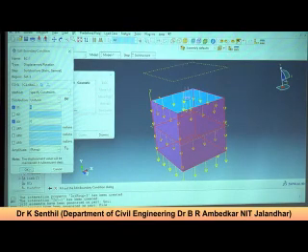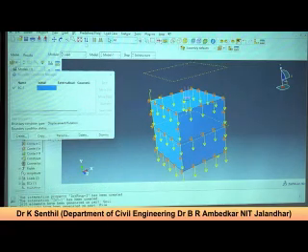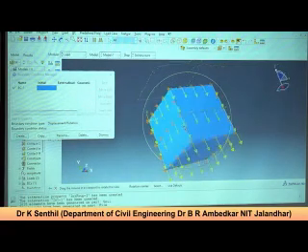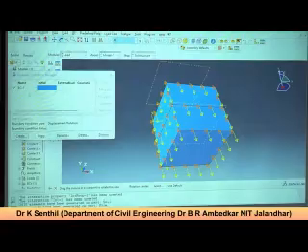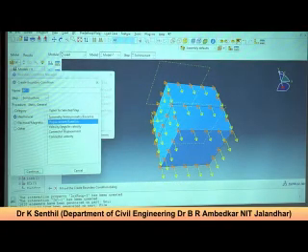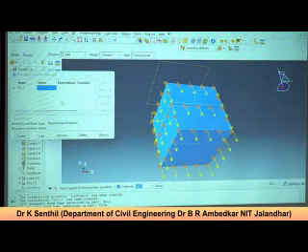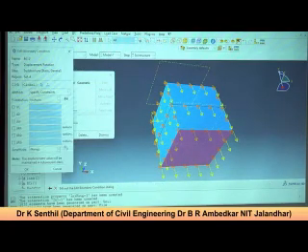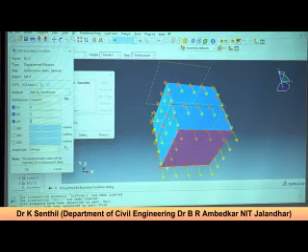Done. Now it's okay. Now at the bottom, I'll keep it fixed. Create displacement. You can select the surface and then do it. So that's all. Encastre also is okay. All three I'll keep 0.